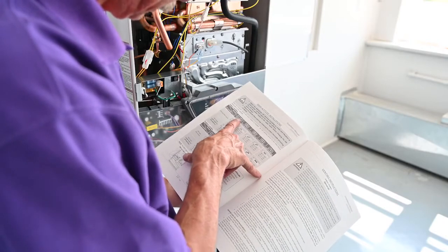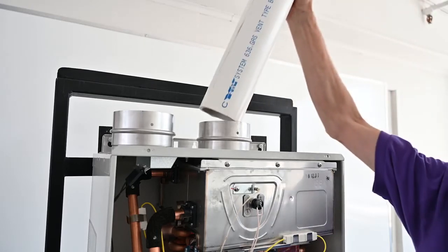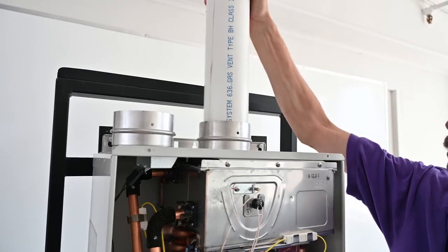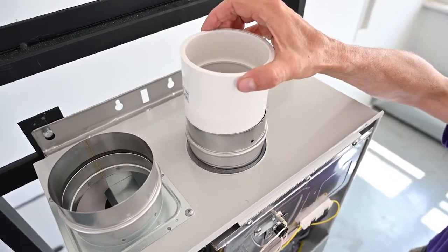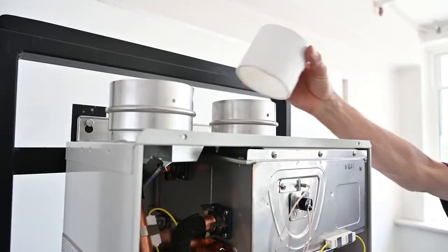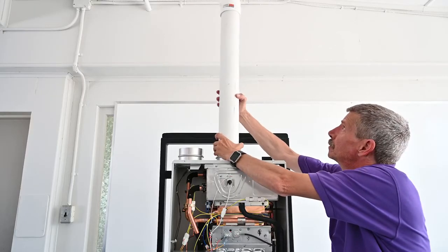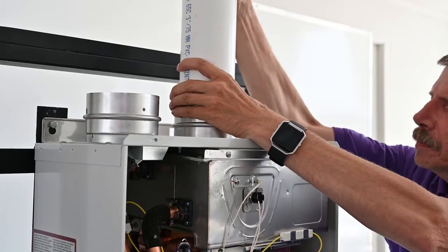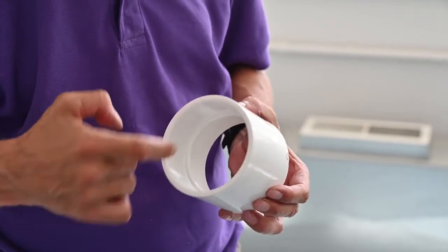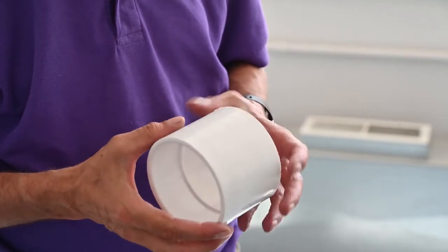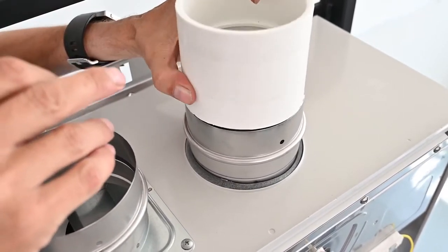the included installation manual. It is important to note that a vent coupling must be used to correctly connect the venting to the metal vent collar of our tankless units. Simply insert the coupling into the metal vent collar on the tankless unit. No screwing, gluing, or clamping is required. Then, attach the remaining vent pipe normally. The built-in gasket in the vent collar makes the seal. A standard Schedule 40 3x3 PVC coupling is shown here. Other couplings may be used based on the desired vent type and diameter.